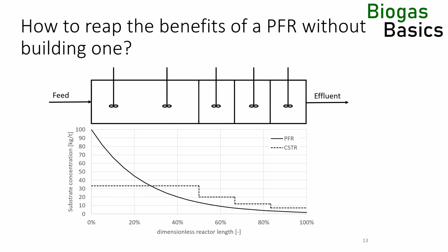The second reason for the larger first compartment is the inoculum requirement. The first CSTR does not have an inoculum stream. Instead, the residence time must be high enough so that the microorganisms of the AD process do not get flushed from the system. I will talk more about washout points and growth rates in the microbial growth presentation. A certain residence time is required to ensure that the microorganisms can grow in a stable environment and do not get flushed from the reactor at the first process disturbance. All downstream reactors will be inoculated from the primary reactor. They do not require a minimum residence time to establish a stable biocenosis, as long as the fermentation conditions, especially temperature, do not change too much.